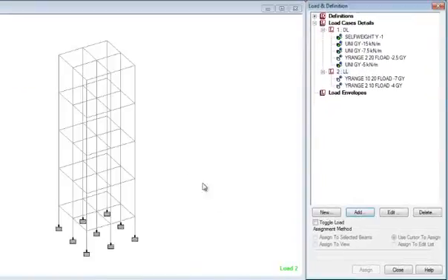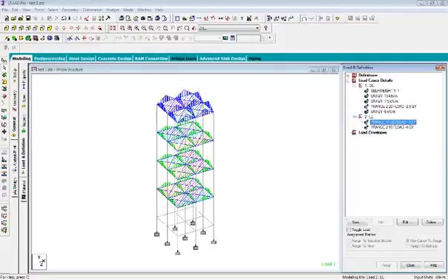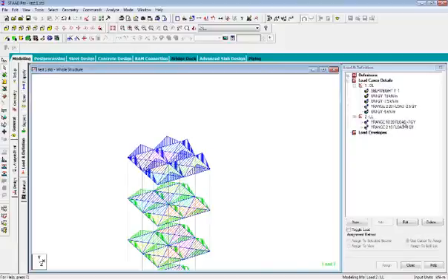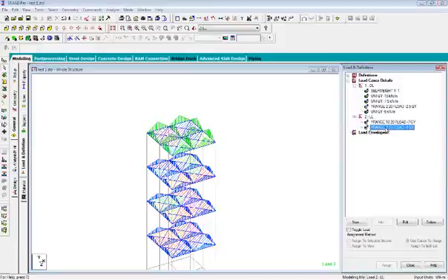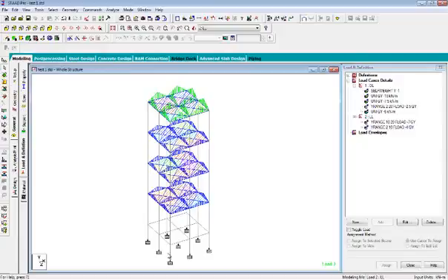So what we now see is this is the first one with minus 7 kilonewton. Just see here, this load is applied on the top floor where we were designing a party space. It will be clearer: the load I am selecting gets highlighted by a blue color. This minus 4 kilonewton is added on the rest of the floors, and on the ground floor, as you all know, there is no live load falling, because this load is directly transferred to the ground. Here this will be transferred to the subsequent beams, and then beams will transfer to the columns.